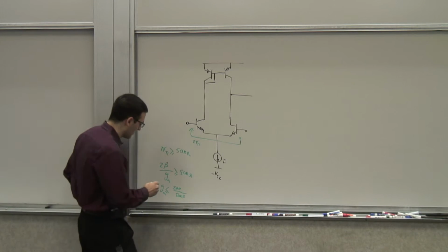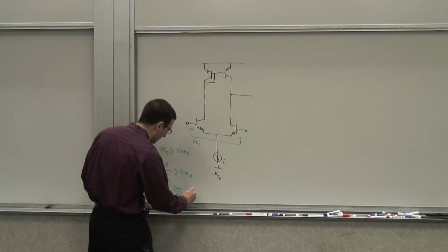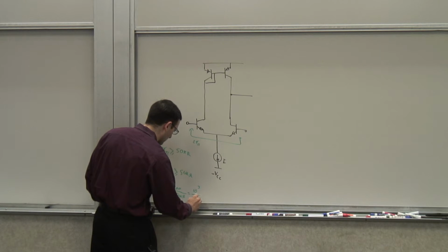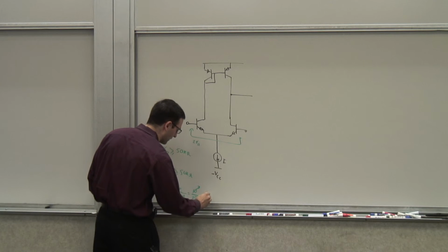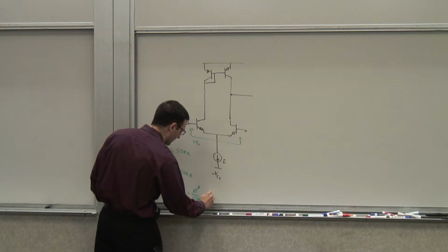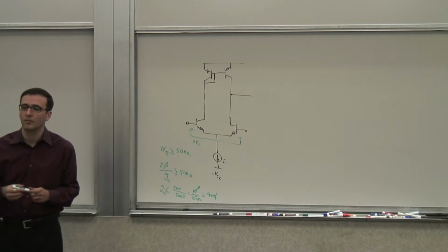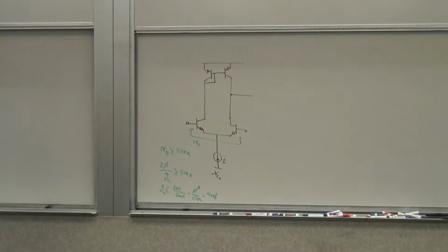Right? So 200 over 50 multiplied by 5 is 1,000 over 250 kilohms. So the kilo cancels, it's 1 over 250. It's 4 millisiemens. Right? So my GM has to be smaller than 4 millisiemens, so I can't have an arbitrarily large GM.